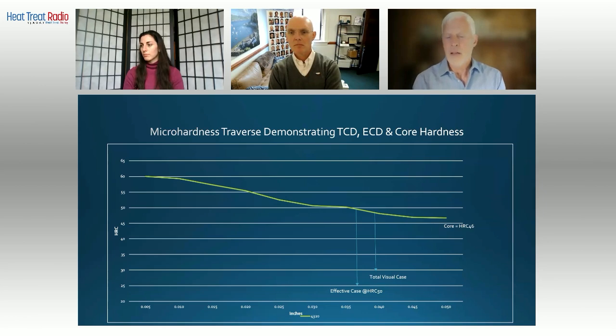But the effective case depth, that's a measurement. And that measurement here in North America, per SAE standard J423, we say that we measure the effective case depth to Rockwell C 50. So you look at the surface hardness is 60.